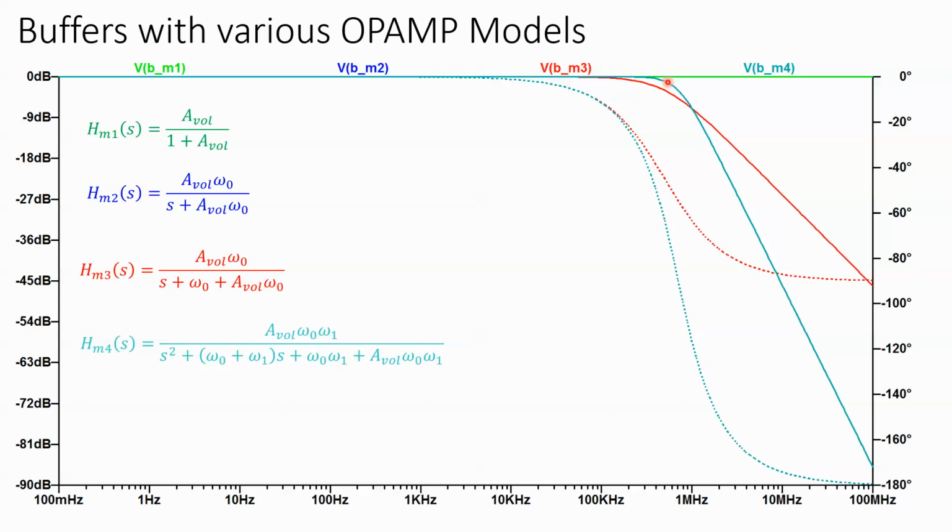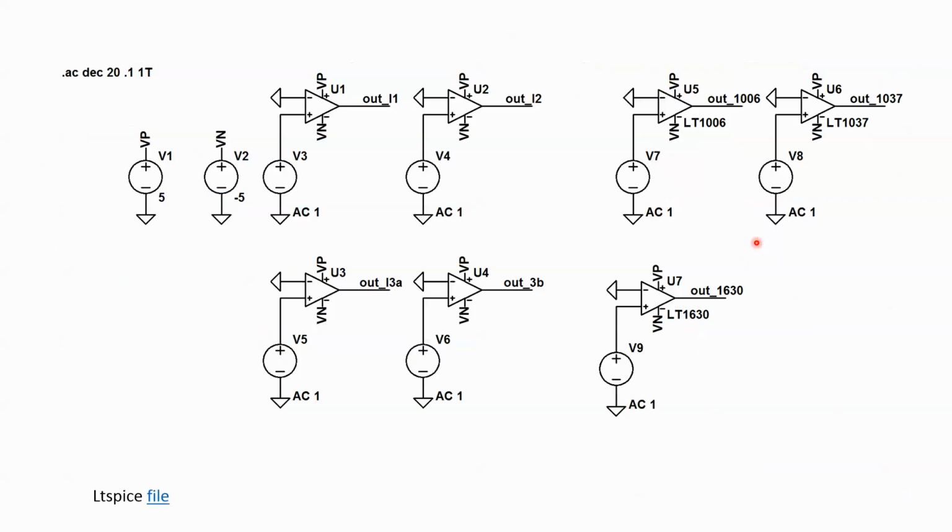But this spot, right, the minus 3 dB point is actually occurring at minus 90, where here the minus 3 dB spot is operating at minus 45. If there were two repeated poles, this would be at minus 6 dB at minus 90. But that's going to be on the final. So we're going to go over that later.